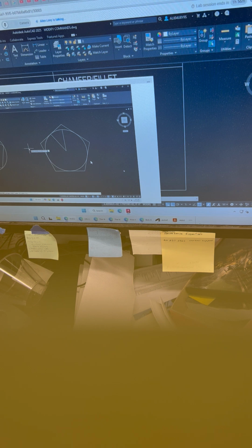And then it says specify the center of the polygon. So just pick some random point inside of that polygon area. Doesn't have to be, yeah, a little bit towards the center perhaps. All right, so just pick a point. All right, now do the inscribe. So you can just select, that's right, just click right on the inscribe.